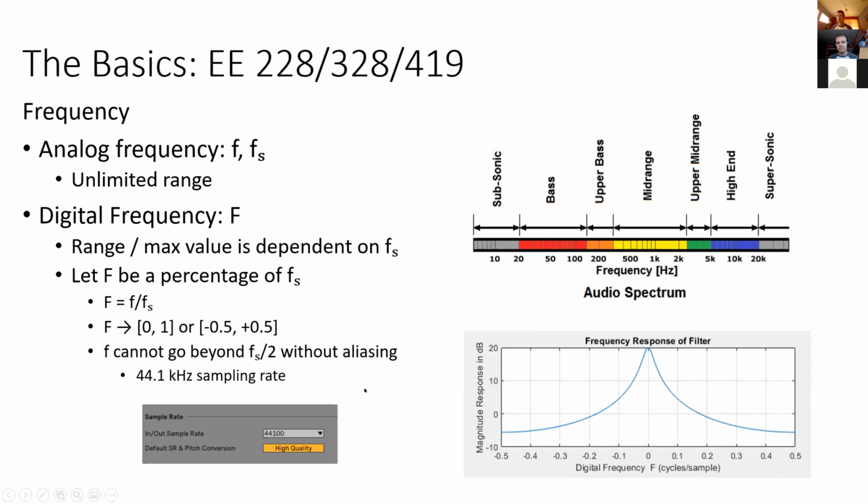Yep. And this just shows you the digital frequency. It's symmetric. And usually, because we can't record past half the sampling rate without aliasing, you're usually just interested in 0 to 0.5, or that kind of chunk.